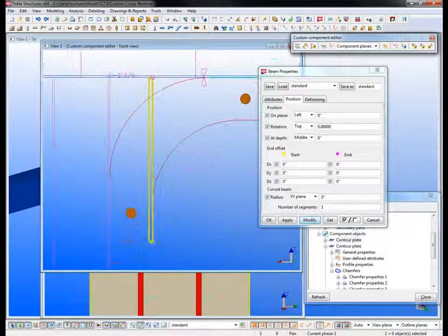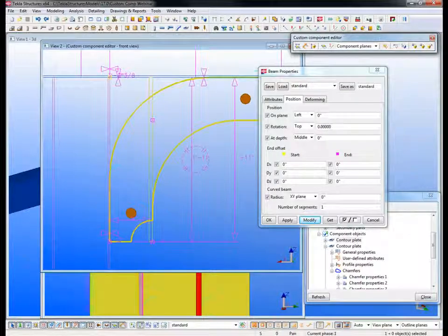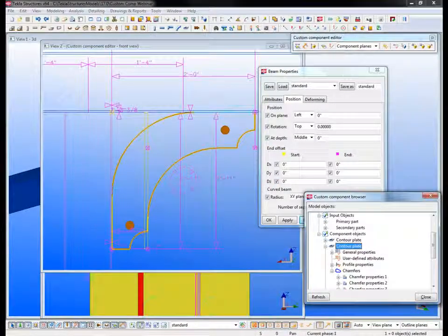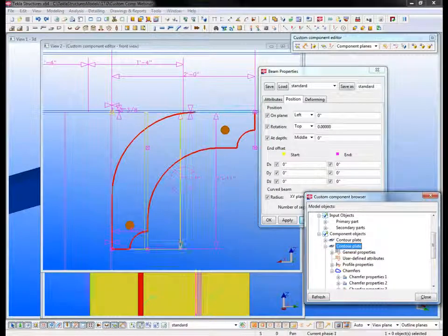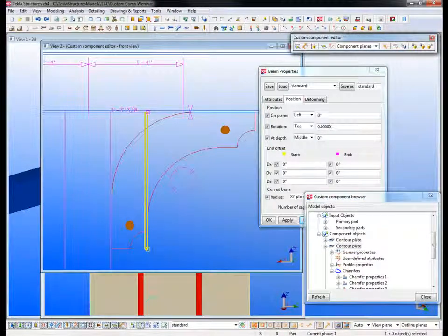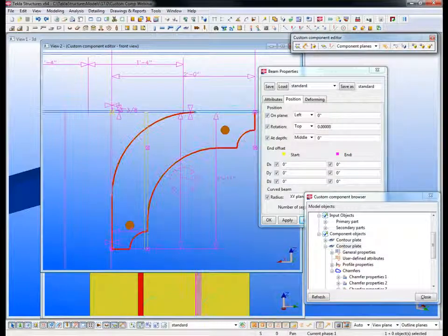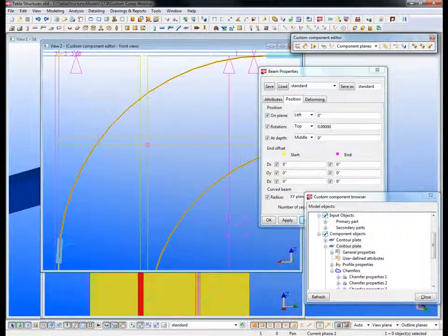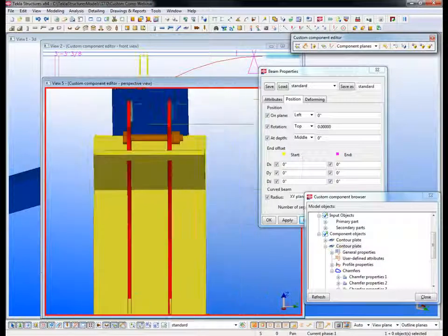So this is one technique you can use whereby you're almost creating a dummy member which won't feature in any of the component, but it just gives you some extra assistance in creating a plane or something like that, just to make the actual creation of the component easier. Yeah. And I'm modeling this with matching the same handles, so that the distance here, this 1 foot 11 binding, I'll be able to apply the same thing here and control them. But what I'm going to do is create with these plates an intersection right here of these points. So let me place that in. So now I can bind to these faces here to control these handles. So I'll go ahead and jump back.